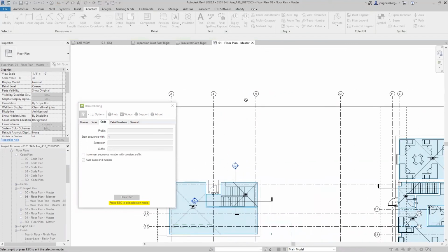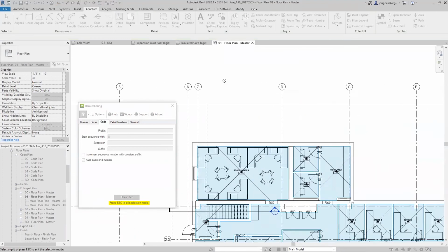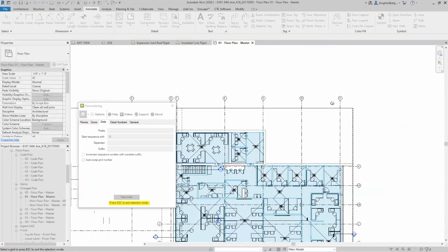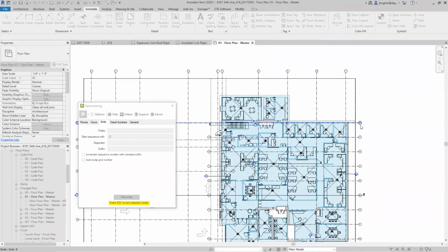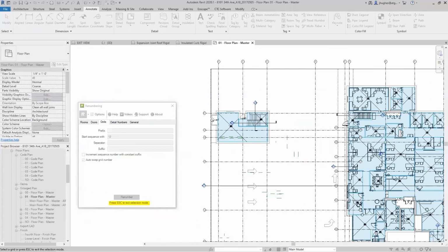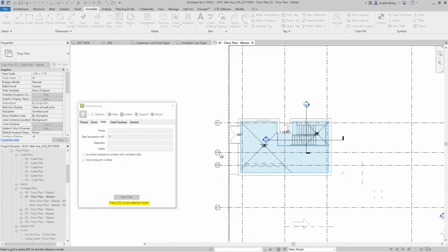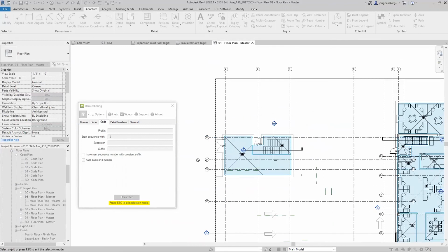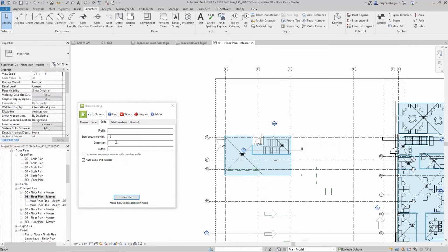And as a non-structural engineer, it lets me wreak my havoc on the rest of the plan. So maybe a bad thing that this one's in the hands of all Revit users, but especially if you've got a large project that has many grid lines in it, you're never going to receive that error that makes you renumber, which is what causes, if we're honest, structural engineers to make 2.4 and 2.5. They're just too lazy to resequence it all. So they just create a unique number inside of that. Here, I can make this one K, L, M, and just keep going. Hit escape when you're done. And this will handle grid numbers. I've already shown you three ways it does this.